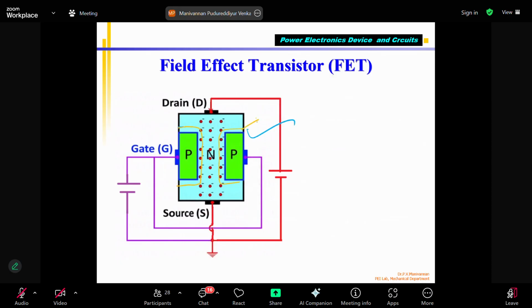Correct? This is for VGS equal to 0. So this should be minus. This is only one small correction. We make it plus minus. This is my VGS. This is VDS, plus minus. I give a supply of 10 volts. I vary VGS from 0 to minus 4 volts or 5 volts. Okay, so this is for VGS equal to 0. Next thing, what will you show? For example, the next one, VGS equal to this much region, that is VGS equal to -1 volt.